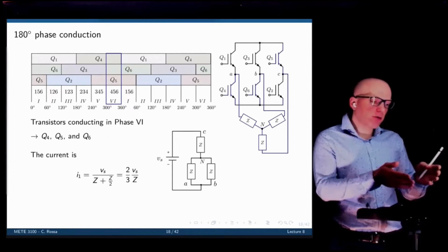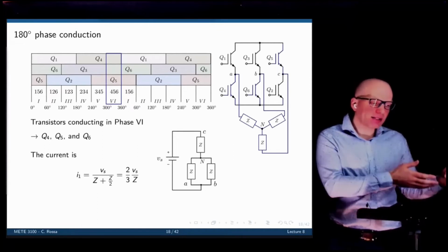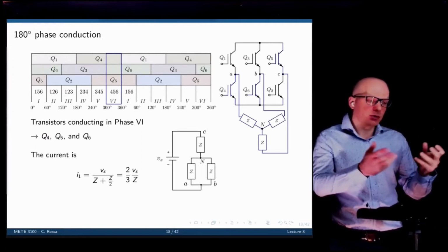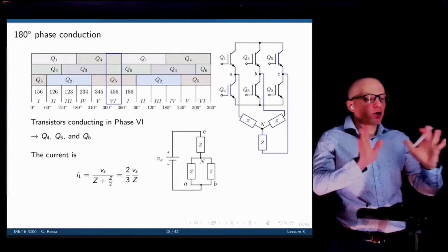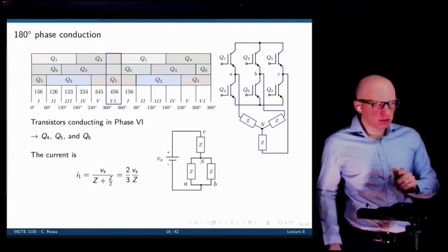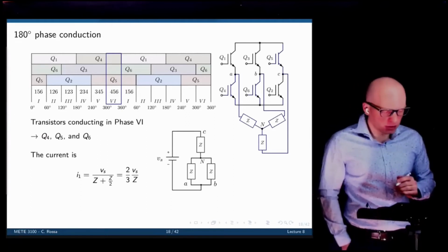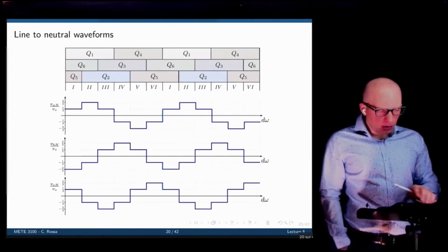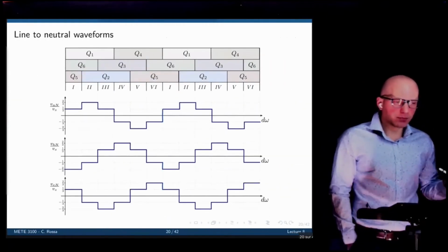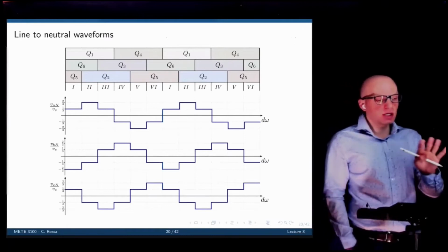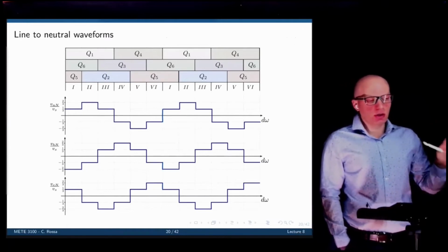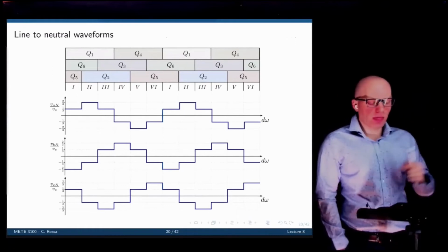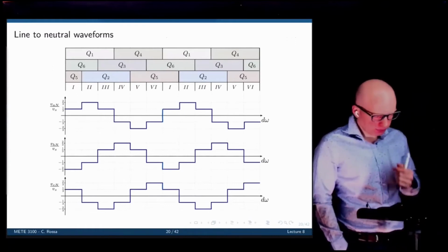In this specific case, I'm showing this in terms of omega t, not time, so that becomes radians per second, just to avoid references to frequencies that right now don't need to be specified. Okay, so these are all the phases we got: 6 phases, 6 possible combinations, and 6 possible resulting voltage combinations across the load.